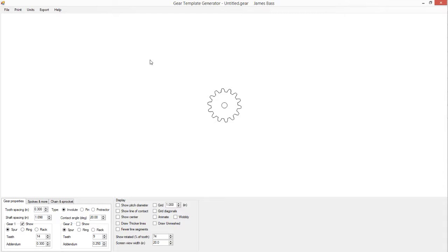Something to remember: now, what we have to do is export this as a basic DXF. Don't try it with the polyline, because apparently this program plays around with different kinds of polylines. I haven't really been successful with exporting as a polyline, but as a basic DXF drawing. You can see it'll give you various others. You can go with a PDF or HPGL.